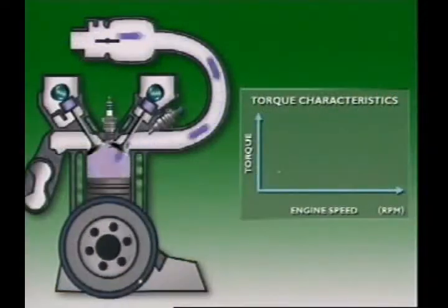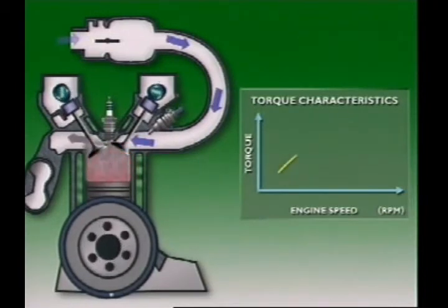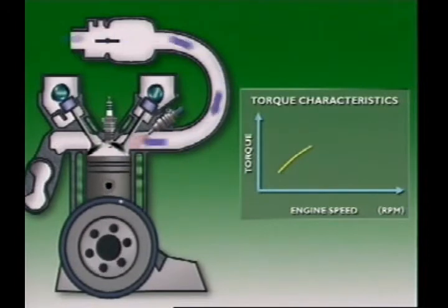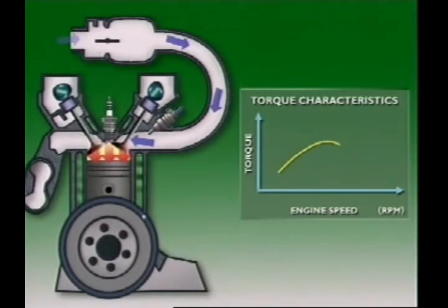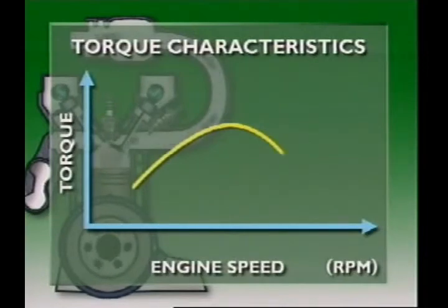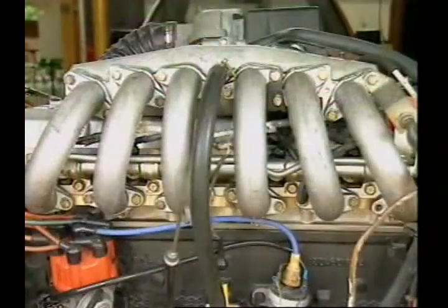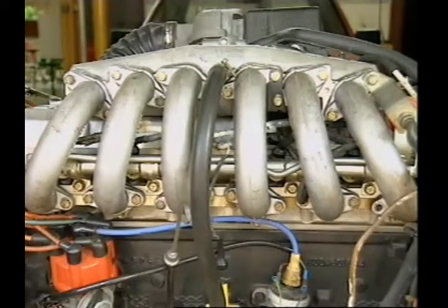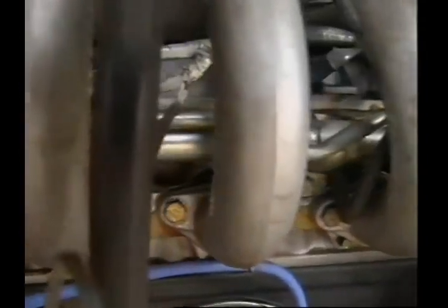The more air drawn into the cylinder, the denser is the air-fuel mixture when the inlet valve closes. And it's this density of the air-fuel mixture that determines how much pressure develops in the cylinder during combustion and the level of thrust on the piston to turn the crankshaft. The characteristic torque curve of a naturally aspirated engine depends mainly on how the engine's mean pressure changes across the RPM band. The design of the inlet system largely determines the mass of air that can be drawn into a cylinder at a given engine speed. So that means the inlet system largely determines the engine's torque curve.